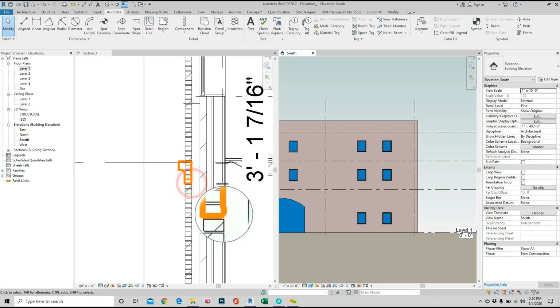You see, the only way for you to know if what you're designing is coursing is by going into here and measuring those things and aligning them with your brick. Notice what I did as well. I put it inside my wall, because if this is a stone, I'm replacing brick for stone. Okay, so right now I go right away and check it out. So I can come right here, and in your sketch you'll find out, okay, what is that distance.